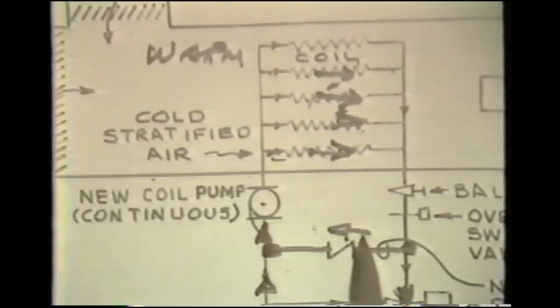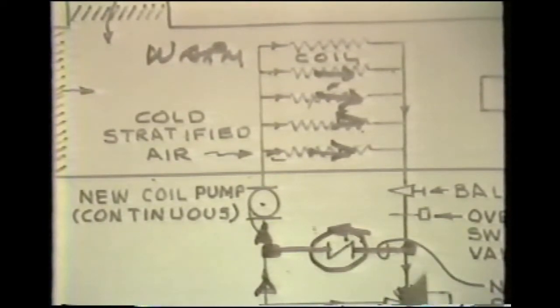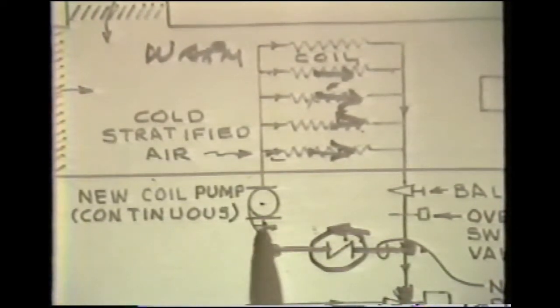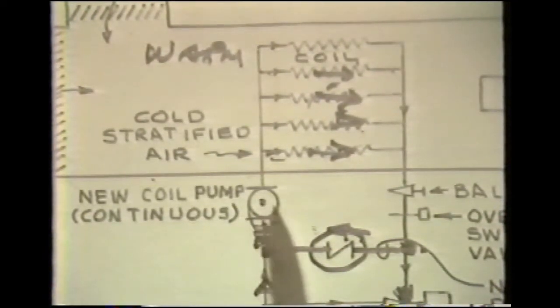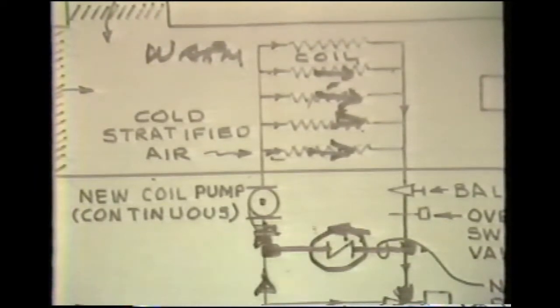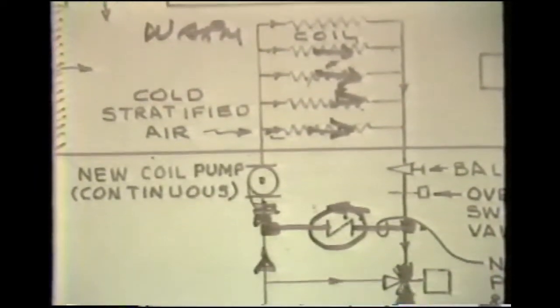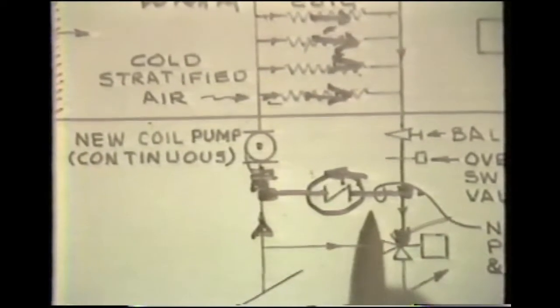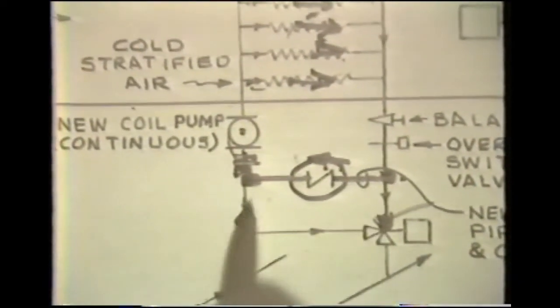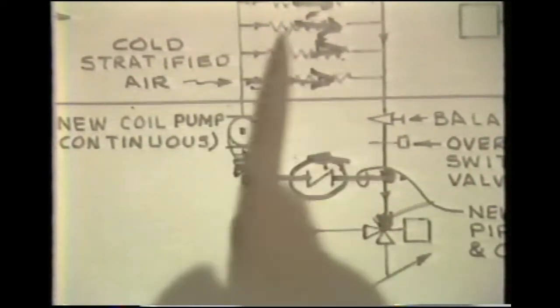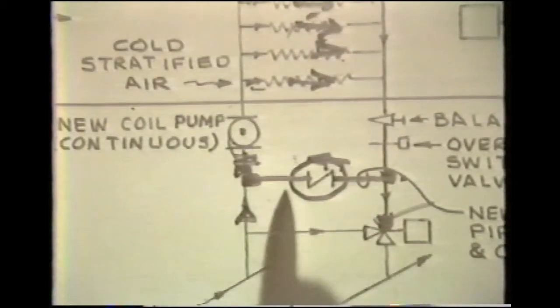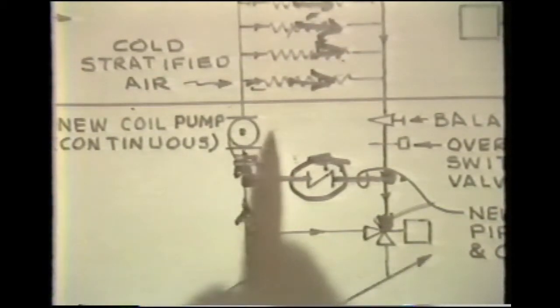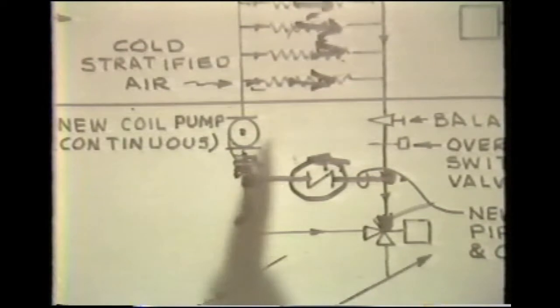We should employ for this circumstance a check valve in the common piping. And that check valve, in association with a flow meter, should the pump stop, the valve can be set to an open position through control methods, so that we do establish a flow of water through the coil even with the pump stopped.